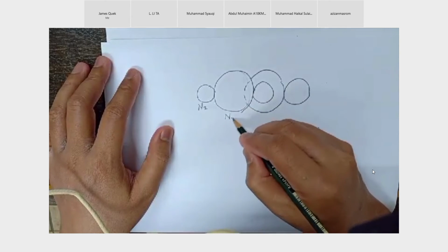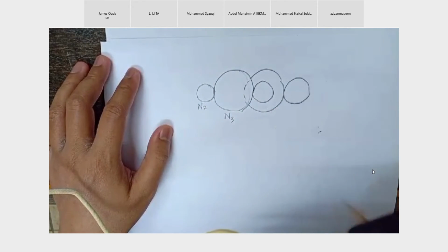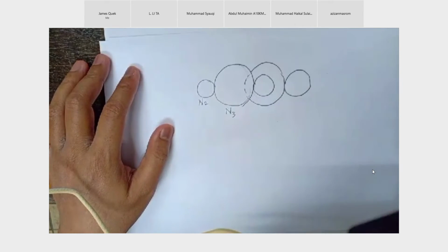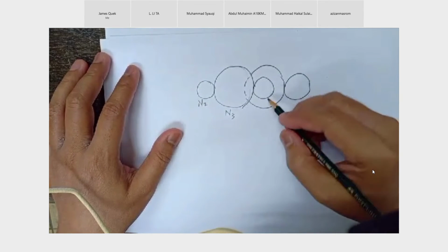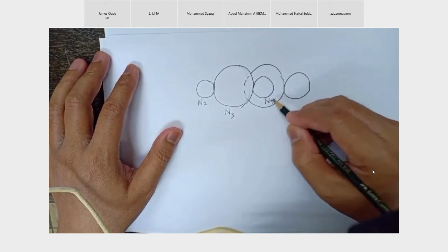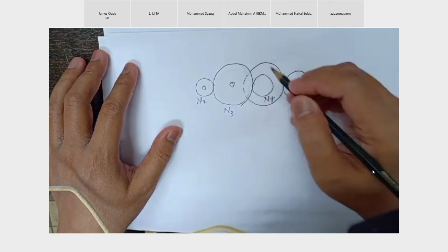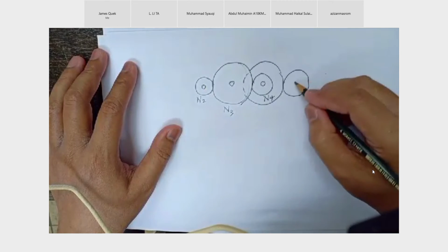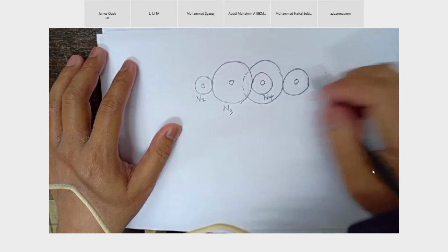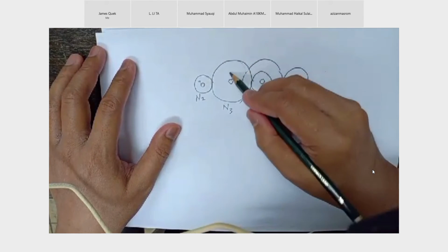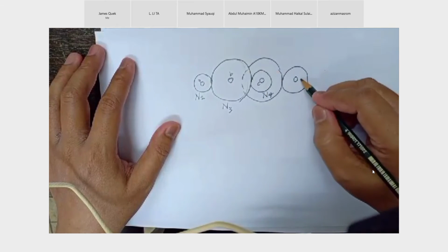This N is the number of teeth. This one is N4 on the front. Because you have a shaft here, gears are always mounted on a shaft. This one is mounted on shaft C, this one shaft D. This is shaft A, shaft B, shaft C, shaft D.